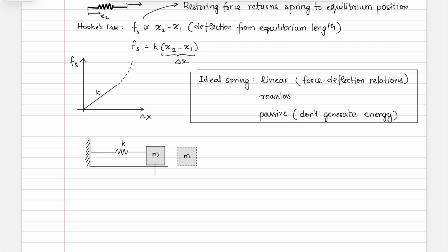We only care about its position, we don't care about its orientation and so on. Throughout the case where you have mass spring dampers in this course, we're going to be dealing with it as just a particle where its position matters, but its orientation and the angles do not matter. So let's say that from its equilibrium position, which I'm going to mark EP, we were to move it to the right by some distance x. To mark the same position I'm marking it here. So when you've drawn a reference as shown here and then you mark an arrow to the right, it means that when you're measuring to the right, your measurement is positive. If you were to measure to the left, your measurement would be negative.